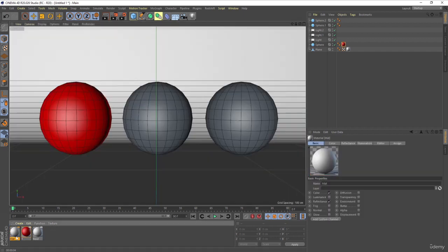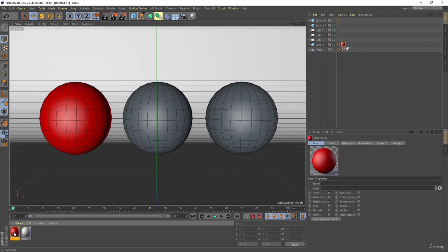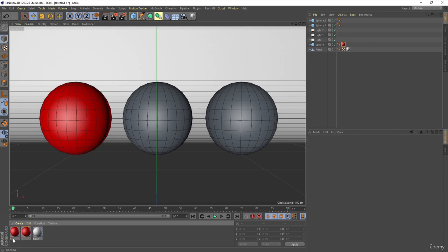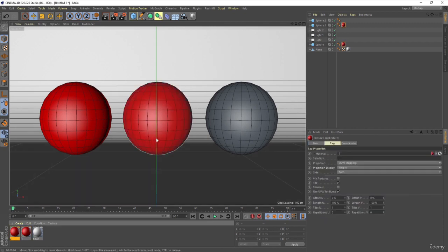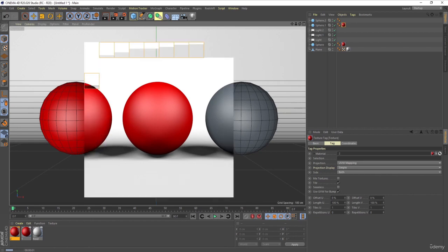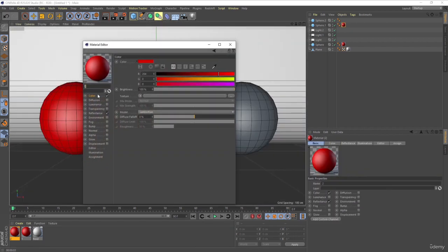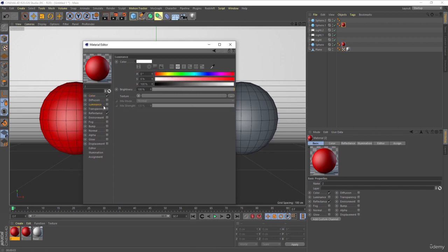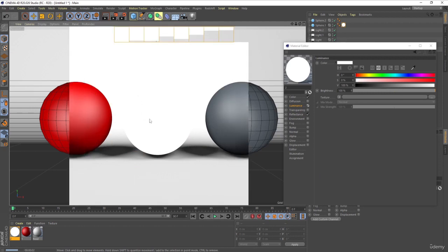So from this we can understand that this is a three-dimensional object. If you want to create a duplicate of this color also, simply by holding Control you can move this over here, so it will create a duplicate, and you can name it 2. Now if I apply this color to here and hit Control R, obviously we will get the same result. But suppose you go to the color of the material editor, and you will get this option known as luminance, and if you enable it, as you guys can see over here, this color looks different. And if you hit Control R over here, you cannot see anything.